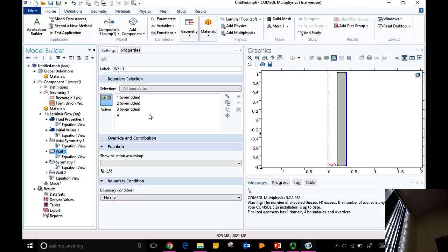Okay? But if I put this additional constraint that the fluid was initially at rest and I start moving the two cylinders, the moment I start moving the cylinders, the fluid next to them will start moving with that velocity, right? But the fluid at the center should be stationary. That's when you will get your minimum. So the profile would be something like this, at a very short time at the start.